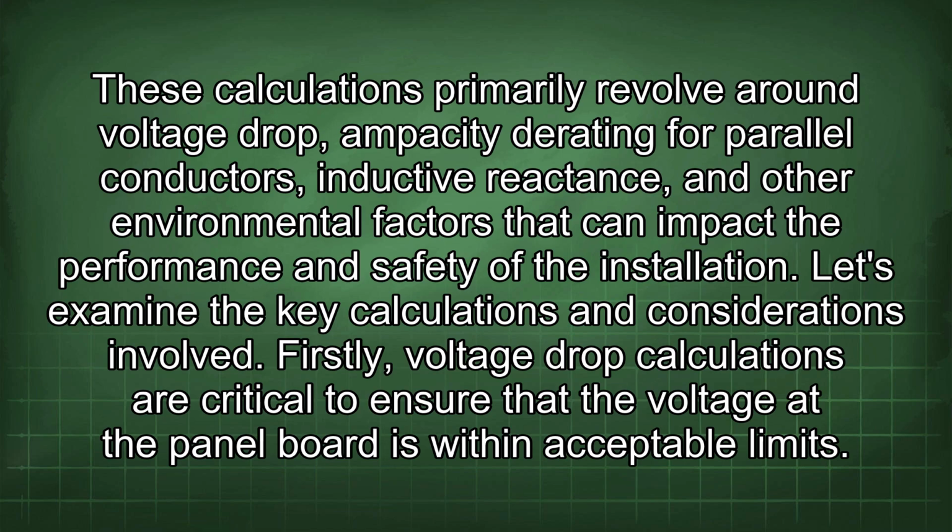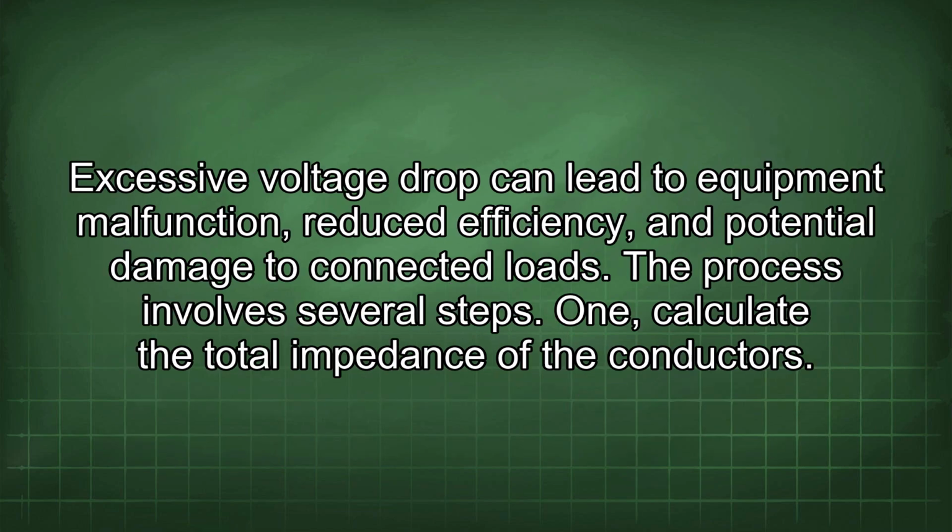Firstly, voltage drop calculations are critical to ensure that the voltage at the panel board is within acceptable limits. Excessive voltage drop can lead to equipment malfunction, reduced efficiency, and potential damage to connected loads. The process involves several steps. 1. Calculate the total impedance of the conductors.